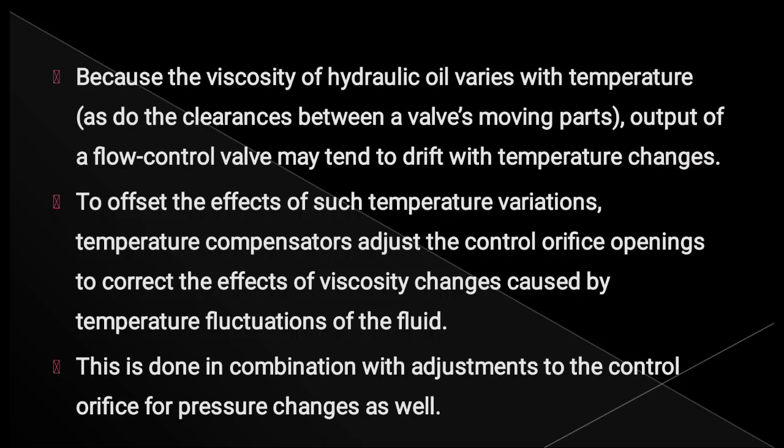So to avoid that effect of viscosity on the actuator, we use the temperature compensating element. That is what is used here. To offset the effect of such temperature variations, the temperature compensator adjusts the control orifice opening to correct the effect of viscosity changes caused by the temperature fluctuation of the fluid.